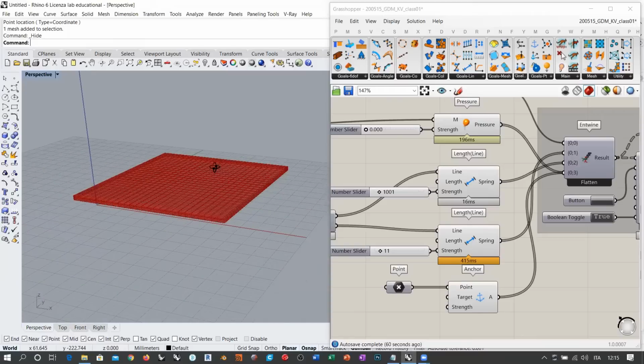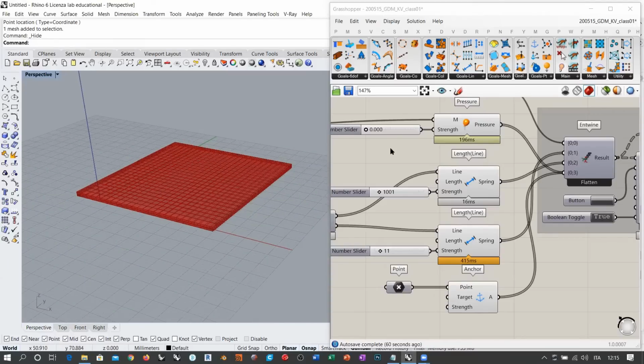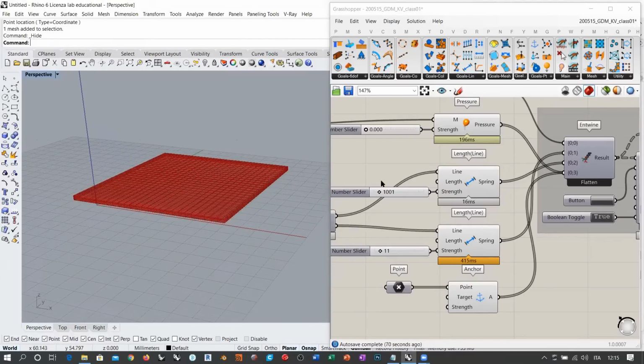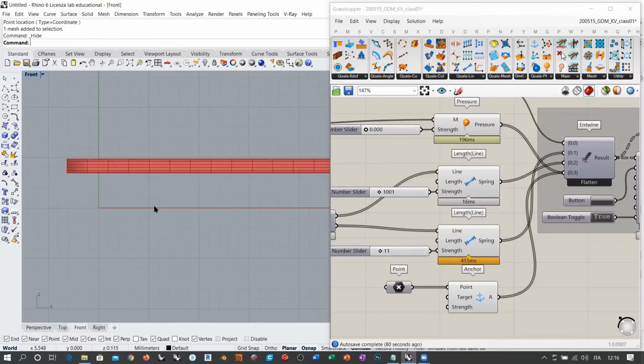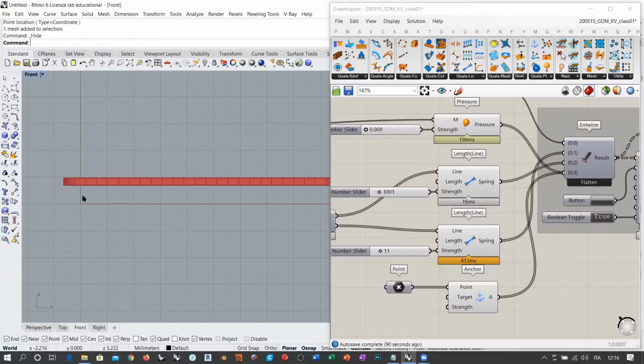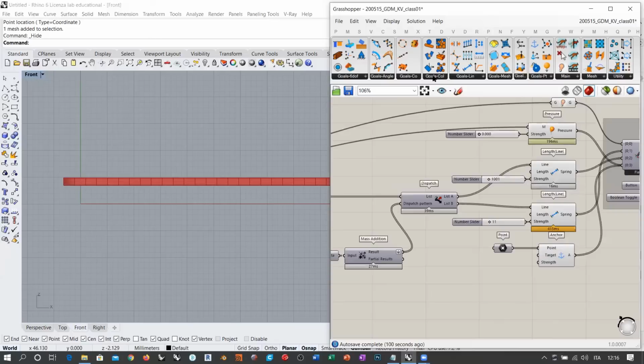But anyway, I'm going to reset this, and what I'm going to do, I'm going to add some floor. Okay, so this object will be only capable of expanding upward. We can do this like using the standard floor component from Kangaroo. But in my case, for example, this object lies at a height of 3 point something. Okay, so if I place a floor, automatically the floor will be placed at the XY orientation of the original world coordinate system. So this object would be able to expand a little down and then, let's say, encounter the floor. But I want this floor to be at this height. So I'm going to take a different goal, which is a